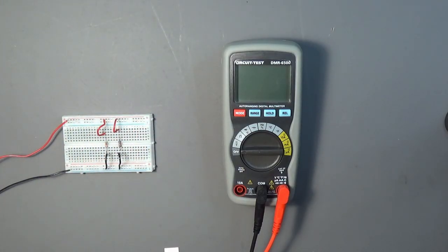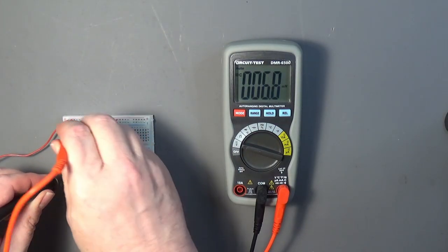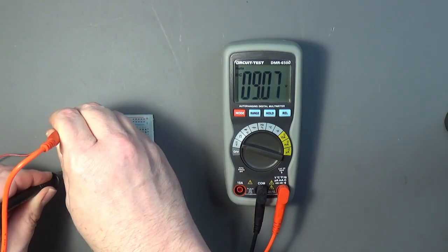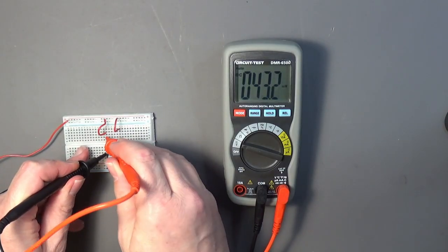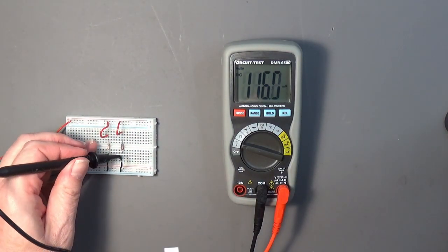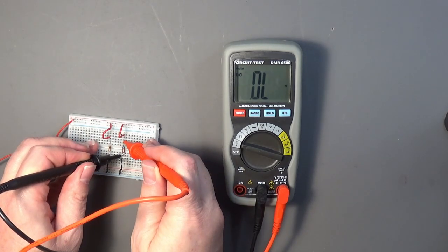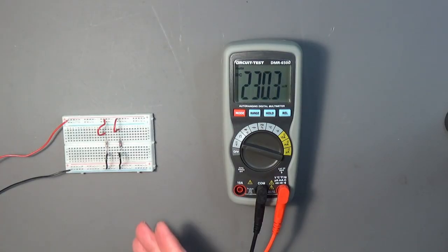So what does things look like here? Well, let's look at the voltage drop. So across the whole circuit, we have a voltage drop of 9 volts, which is what the power supply is. Across our 1K resistor, the voltage drop is also 9 volts, and the voltage drop across our 6.8K resistor, also 9 volts. So this is why things like our houses are wired in parallel. That way all our light bulbs get the appropriate amount of power and voltage.